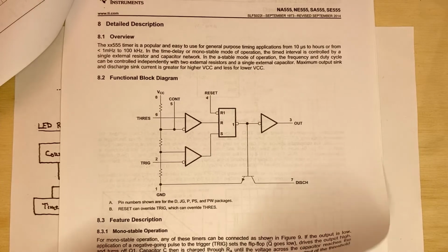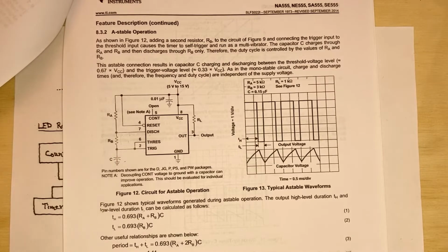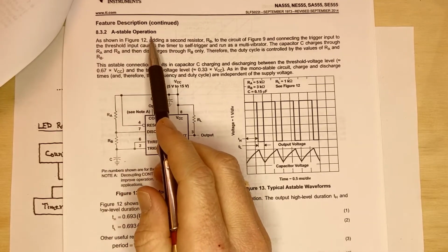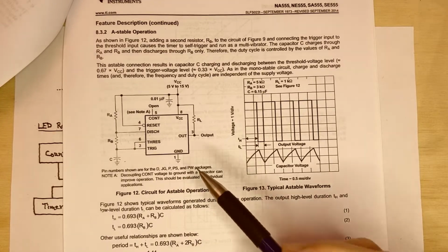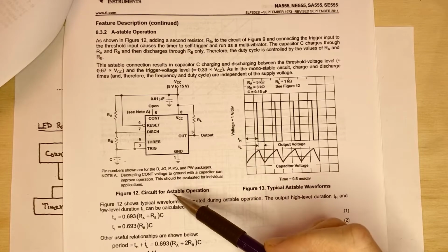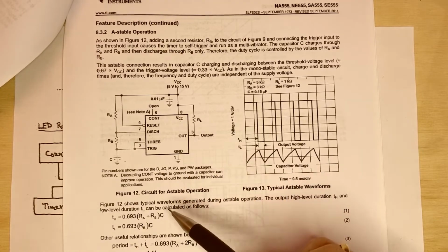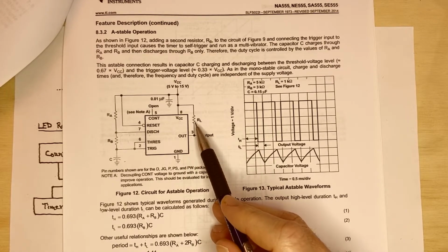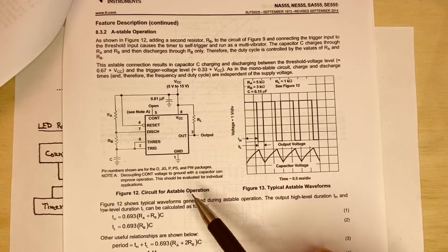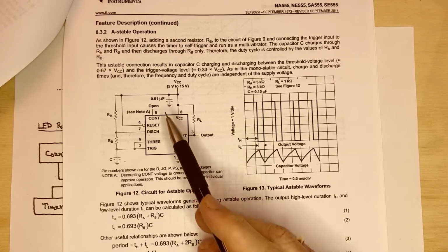And if we continue on to the schematic, it gives a number of examples of what the 555 timer can be used for. And one is the astable operation. And so it has the schematic here of when it's configured for the astable mode. So let's check it out. So we see at pins 1 and 8, those are the power pins. So we stick our ground and our 5 volts up at VCC there. Pin 3 is the output, and here they've drawn a load resistor, which, for now we can ignore, and we could also ignore this coupling capacitor for now.